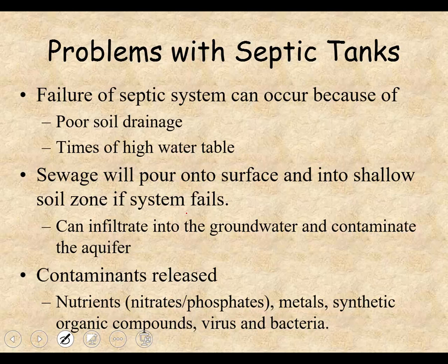So it used to be, well, let me rephrase that. The most recent guidelines require at least 4 feet above any impermeable surface of the water table. Okay, it used to be 2 feet. So you're seeing guidelines changing. And those guidelines, by the way, are typically city or county guidelines, so they'll vary from place to place. Okay?